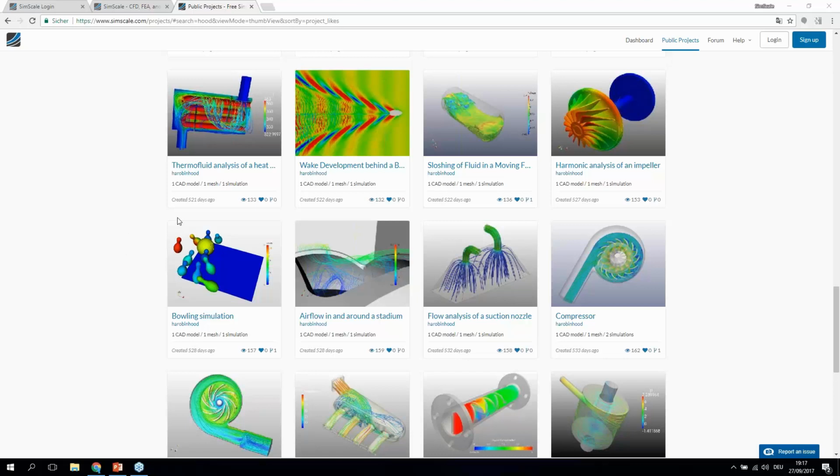Okay, one last question by Claudio. He wants to know what's about the movement of the ship, since it's allowed to trim and sink, and if the hull mesh is dynamically remeshed. No, Claudio, that's not necessary, because in this case we are running a multi-phase simulation. So we are considering this moving of the boat in a different way.